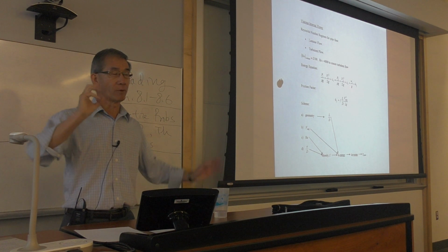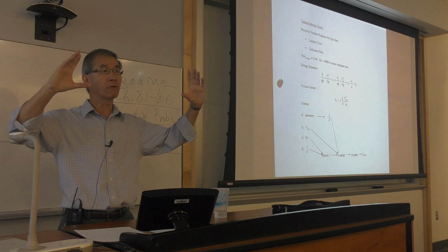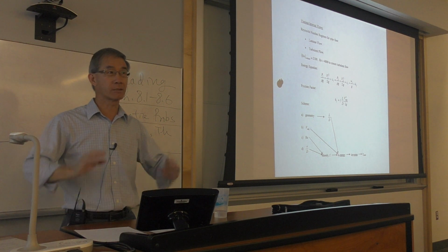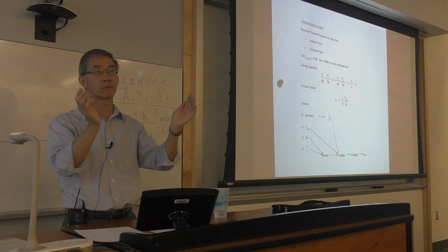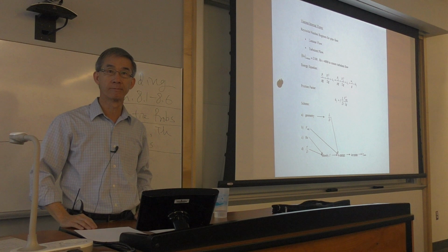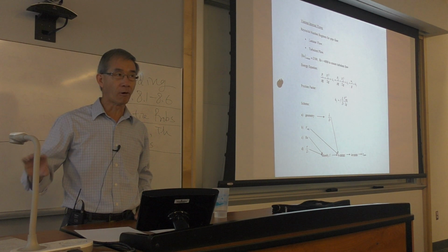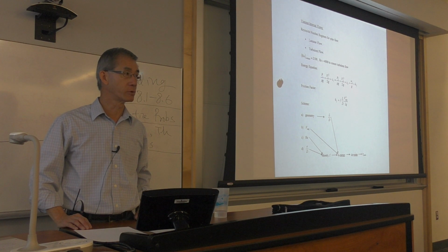For a rectangular duct, like the wood duct you did for homework, we developed this concept of hydraulic diameter, which basically pretends the rectangular pipe is almost like a circular pipe, with a hydraulic diameter given by that equation. But that's only used for determining all the quantities except for continuity.